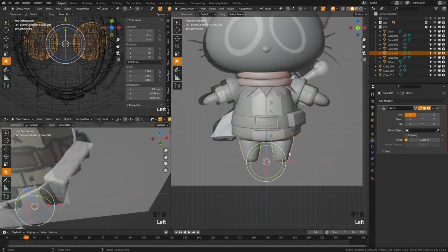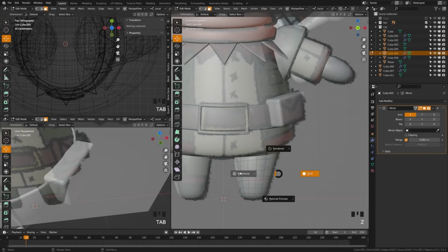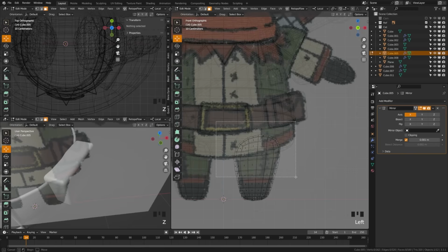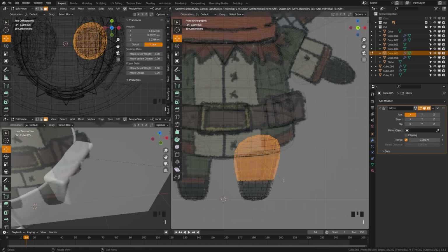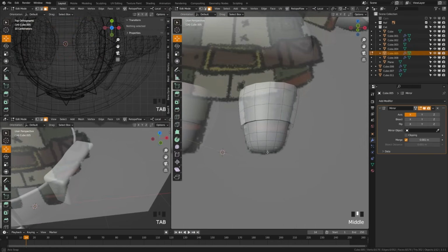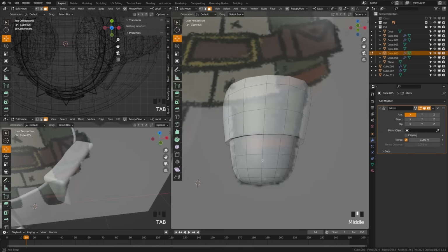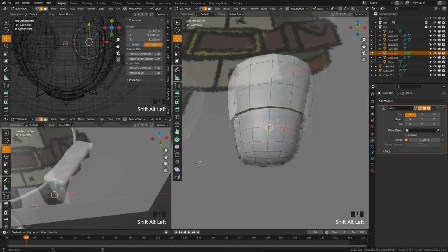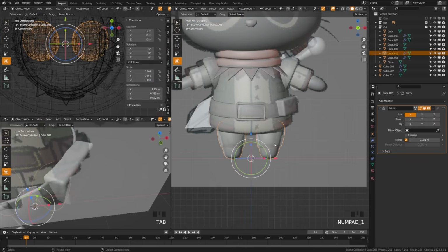Next up, we're going to go ahead and add some shape to the clothes. So let's grab the leg here, switch into wireframe mode. I'm going to go ahead and grab this top view here. And if I press I and Control and drag, we can drag that out. And by doing that, you see we get a little pants edge. You can also switch back in here to edge mode, grab this edge loop here, and if you want, add a bevel, and that'll just help smooth it out and give yourself a little bit more detail.